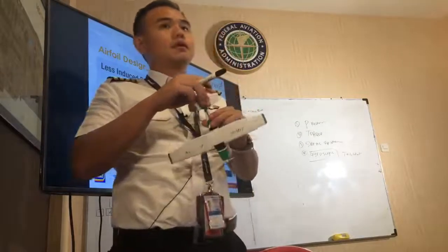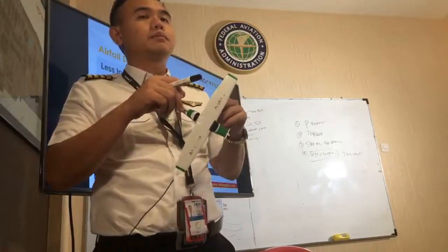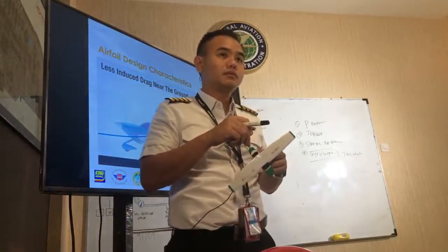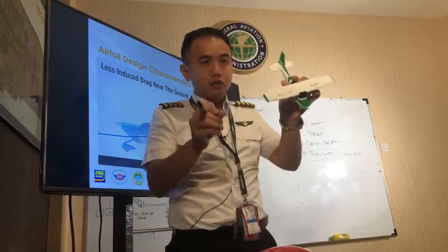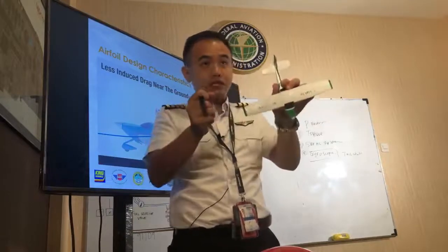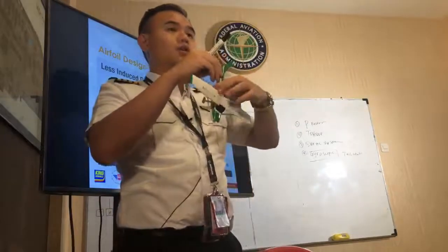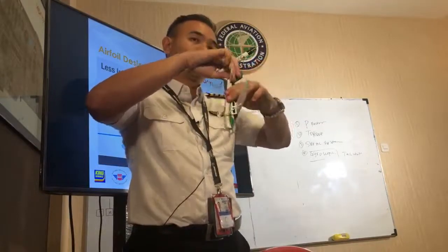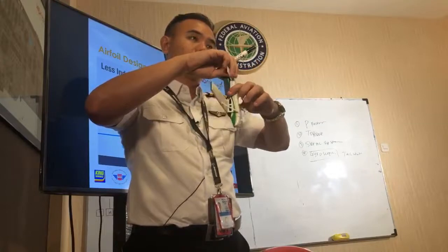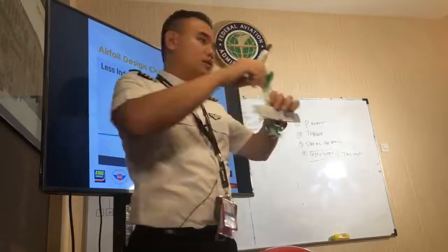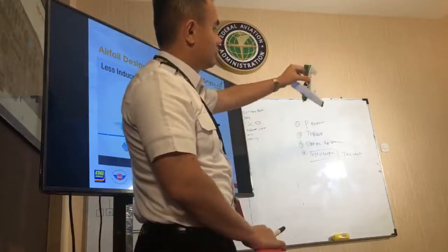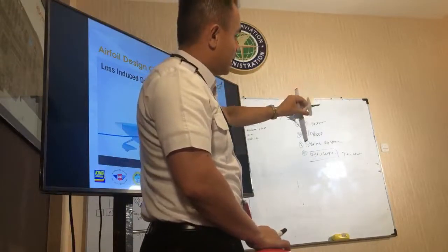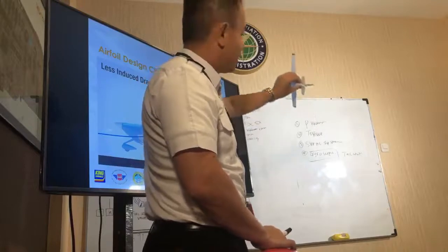Wait. What is PARE? Ailerons neutral. What does neutral mean? You neutralize the yoke and put it to center. And then rudder opposite. So what rudder do you have to kick? At first, the direction of the spin. So opposite. Here the airplane is spinning, so we need to use the right rudder. Kick the right rudder until it stops, and when it stops, it starts like this.